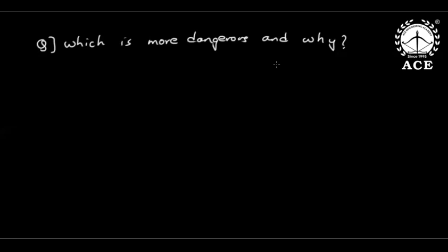We always say, sir, short circuit is dangerous. No, sir. Short circuits will create fire, but short circuits will not create direct loss of life. Because of excess short circuit, fire may come, wire may burn, equipment may burn, and fire may indirectly kill us. But if you design proper equipment like current limiting reactors, fuses, circuit breakers, fire alarms, etc., short circuits are always easy to protect. But open circuits in high voltage, there is no protection because of insulation level. That is why, according to me, open circuits in high voltage engineering are deadly dangerous compared to short circuits.